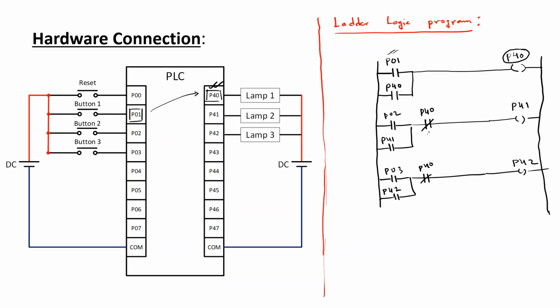So if these contacts are getting transition from their initial state, so if initial state is considered to be 1, after transition they are going to be 0, or in this diagram representation they will become open circuit. Even if participant 2 gives some input, due to the open circuit, there is no continuous path up to the output coil. Similarly for participant 3 as well.